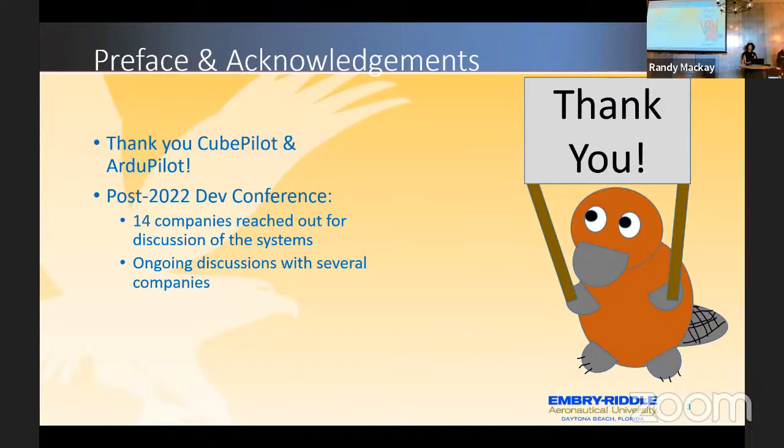Yeah, so the primary link at this point will be CAN. And Siddharth has been putting a lot of work into getting CAN FD across, which speeds things up dramatically and gives us a much heftier bus. And we have multiple CAN buses running. On the Cube Red, we also have a serial bus between the 2 systems so that they can do what needs to be done outside of all of that. We wanted to run it at 2 megabits, with the same block structures, so CAN plus serial gives you a lot of bandwidth.